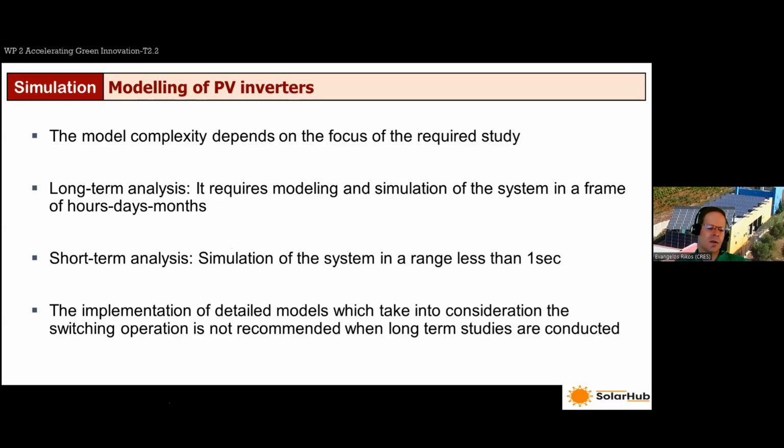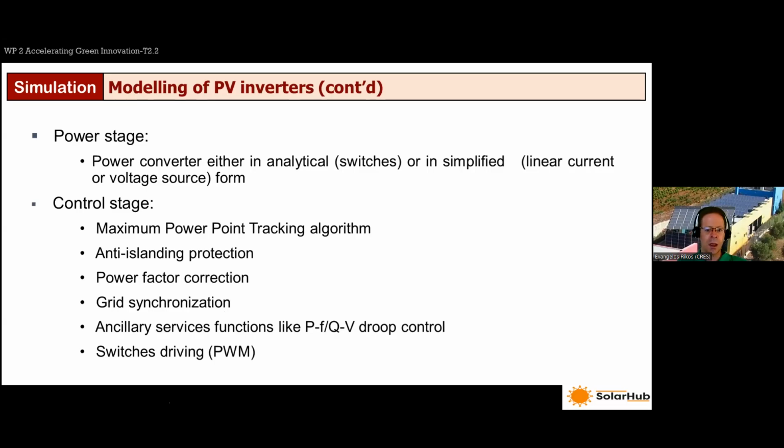In other cases, however, in short-term analysis cases, for example, the simulation of the system in a range less than 1 second, it may be necessary to model the inverter in its detailed model with the switches and everything. It depends on the specific study, I would say. And some other tips about the photovoltaic inverter modeling approach.